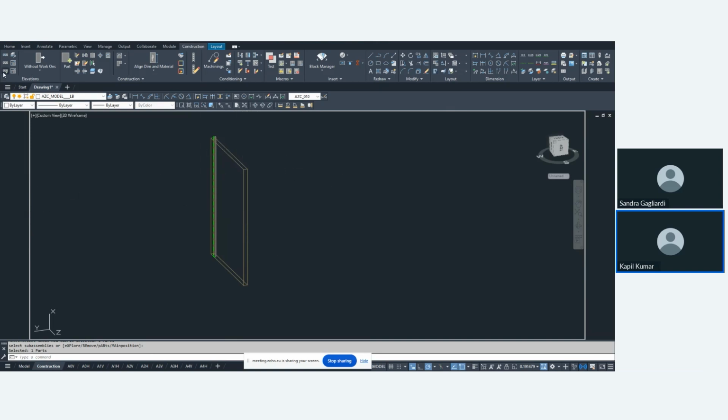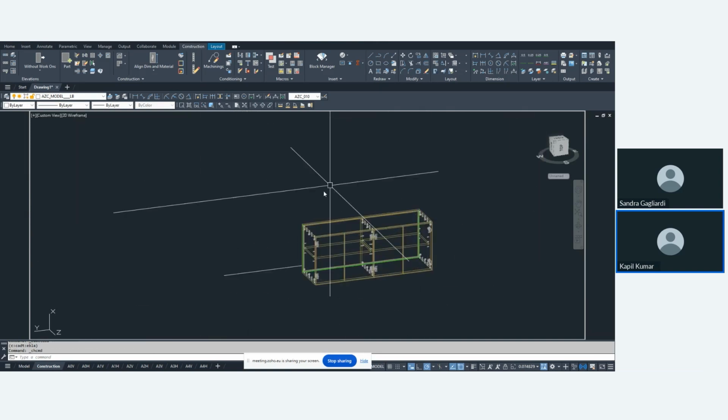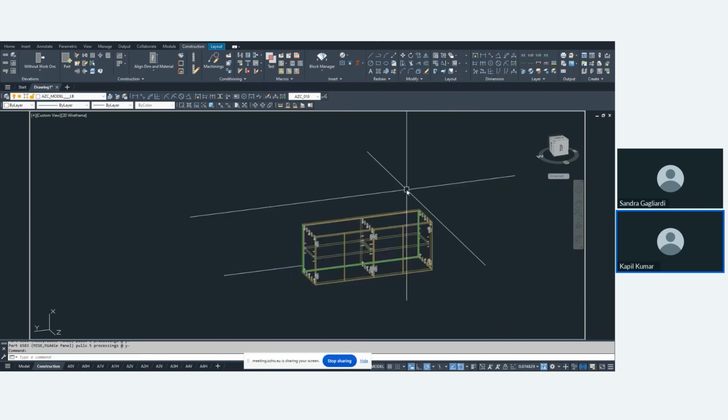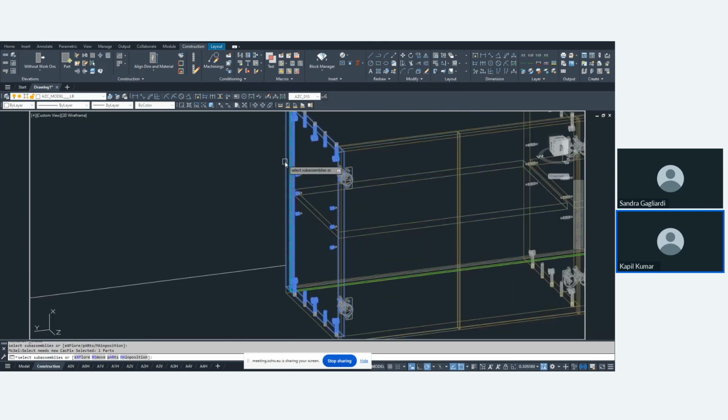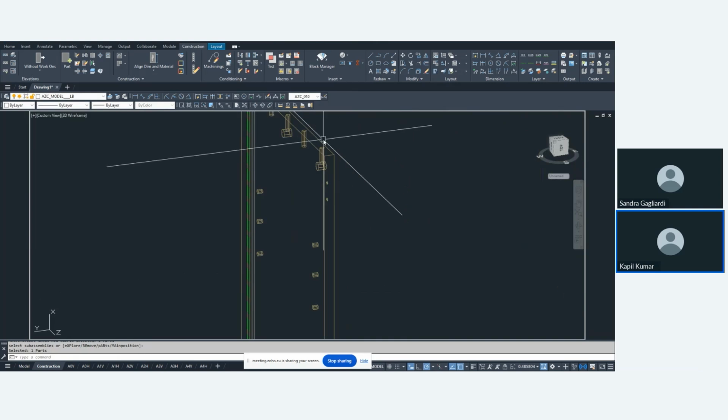For applying that drilling pattern on that part, we have to go here to the analyze macros section. We have two options, analyze macros and macro analysis screen. If we want to clean the existing drill pattern, we can always go here and apply the new configuration again. So now I will apply analyze macros from here, select all the cabinets and press enter. Now I will isolate that side panel here. See, the drill pattern will come automatically this time.